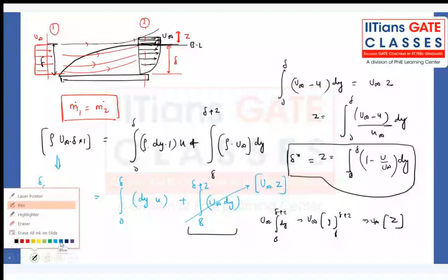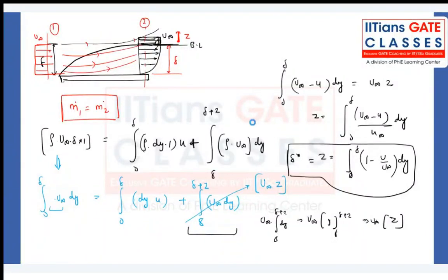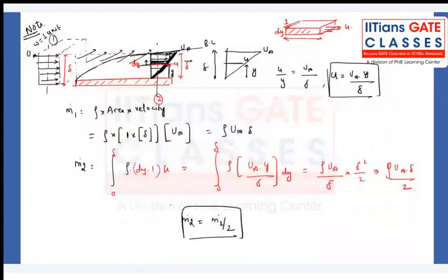So here, my dear friend, just now in our example we have seen that the mass flow rate is being reduced by half. When the mass flow rate is reduced, how can it be increased? Mass flow rate is rho into A into u infinity. I cannot increase rho, I cannot increase u infinity. All I can do with my best effort is provide some extra area. If I provide some extra area at section 2, definitely I can increase my mass flow rate so that it can match with the total mass flow rate at section 1.